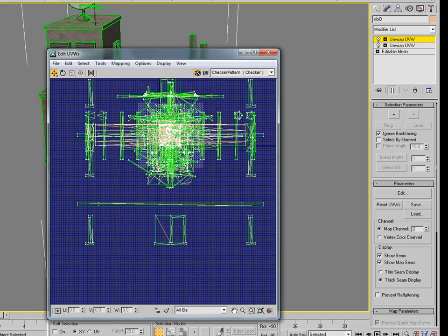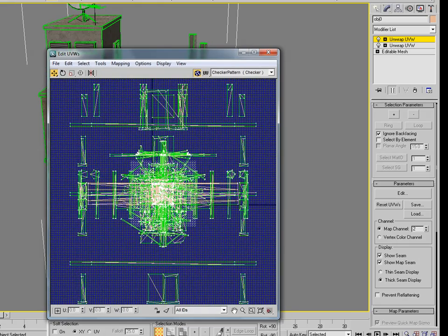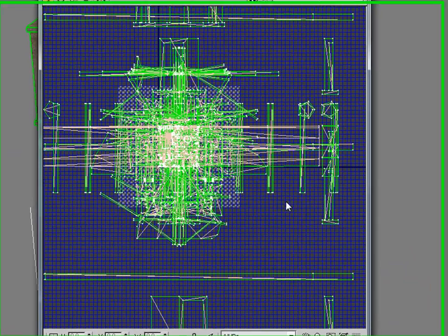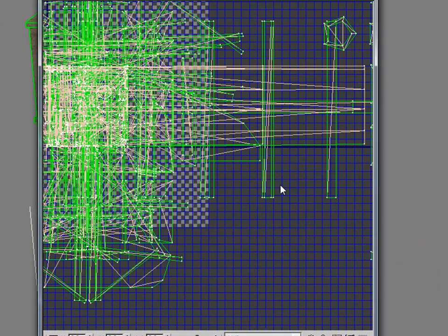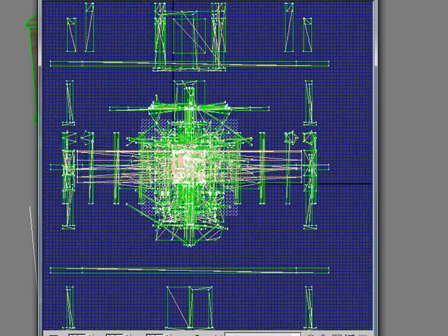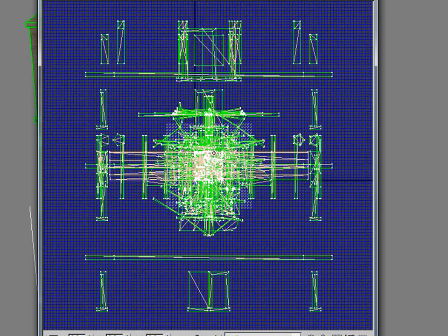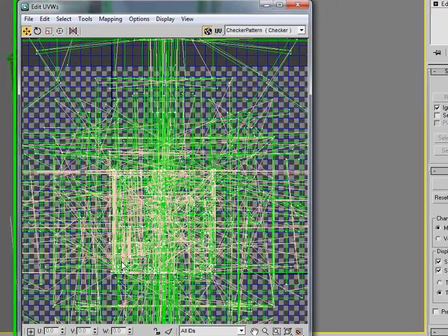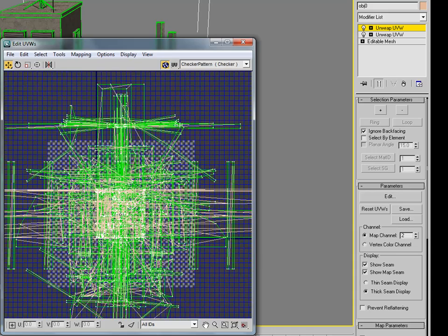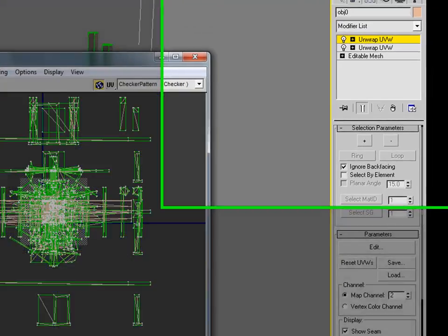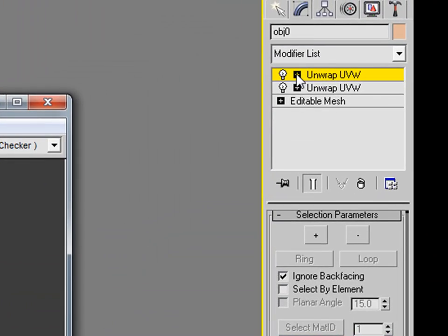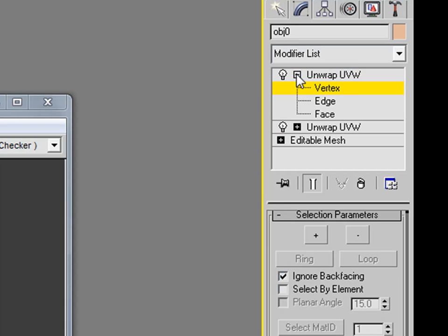And immediately we have two issues here. Our coordinates are overlapping a lot, and to get a proper light map we need to make sure that our faces have unique real estate, they don't overlap at all, and our collection as a whole falls out of our power of 2 desired dimensions for creating a light map, such as 512 by 512, 1024 by 1024, and so on.